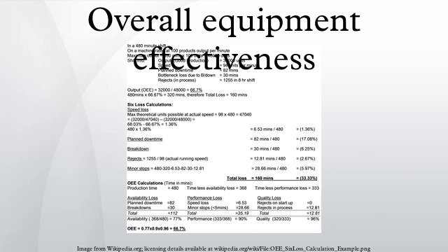Performance/productivity. The performance portion of the OEE metric represents the speed at which the work center runs as a percentage of its design speed. The performance metric is a pure measurement of speed that is designed to exclude the effects of quality and availability. The losses due to wasted performance are also often called speed losses. In practice it is often difficult to determine speed losses, and a common approach is to merely assign the remaining unknown losses as speed losses.